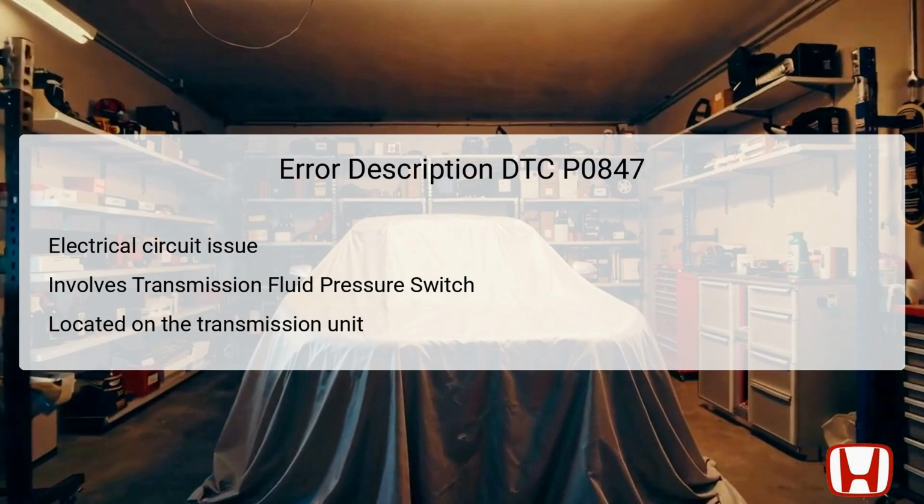When the transmission is functioning correctly, the pressure switch generates a voltage that signals the PCM accordingly. If the circuit is not functioning correctly due to low voltage or short circuits, it can trigger this specific DTC.